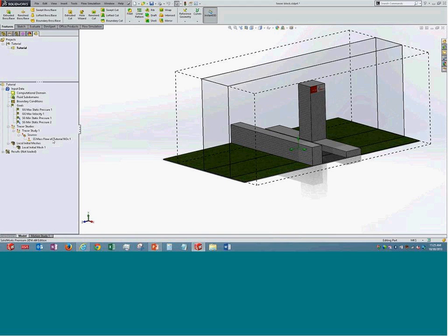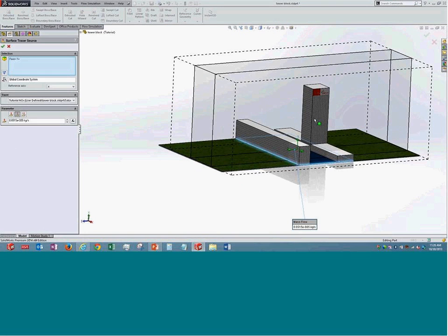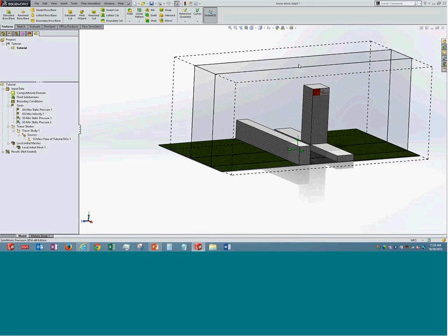So this is the example. Second, we can also visualize this part of it. In terms of parameters, instead of velocity, we take that particular parameter, nitrogen oxide, and see the variation of nitrogen oxide inside the system. That can help us understand how clean the streets will be, and if it is a closed space, whether the human beings present there are exposed to too much nitrogen oxide, which can lead to some health problems.